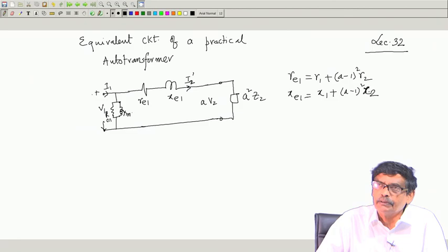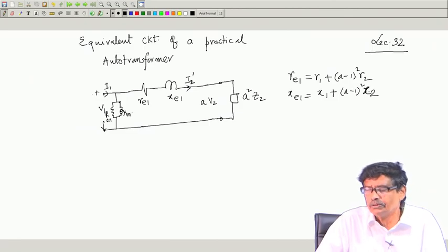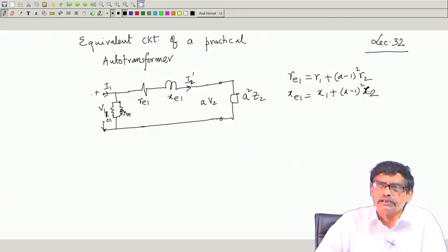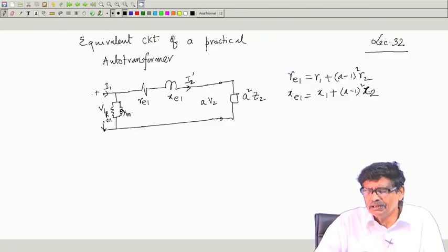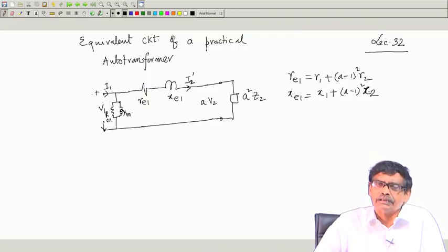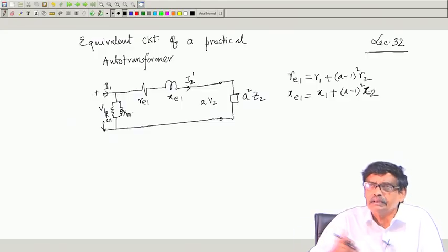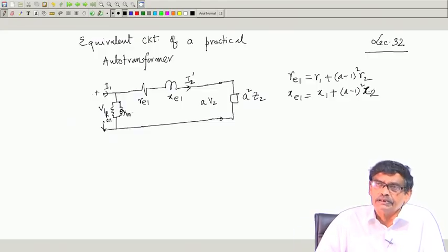Although you can change the level of voltage from one level to another for any ratios, theoretically it is possible, but there are some advantages of auto transformer when the voltage ratios are not differing too much, then you choose auto transformer. Then also isolation problem we can easily see is not that urgent, at the same time economically it will be much attractive, and a two winding transformer on the other hand gives you the isolation where it is needed.